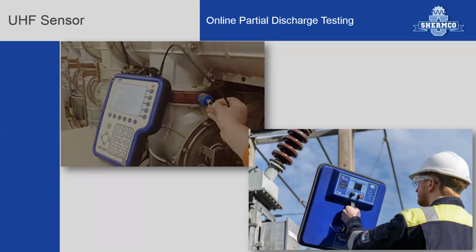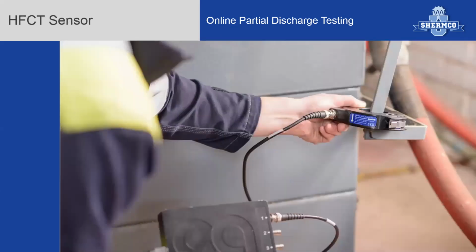In some cases, such as inside of a power transformer, the UHF emission may be completely shielded by the sealed metal enclosure of the transformer. Well, fortunately, the UHF signal will also induce a high-frequency current pulse onto the grounds of the apparatus. The high-frequency current pulse will be detectable with a special high-frequency CT, referred to as an HFCT. And that leads us into the next sensor, the HFCT sensor.